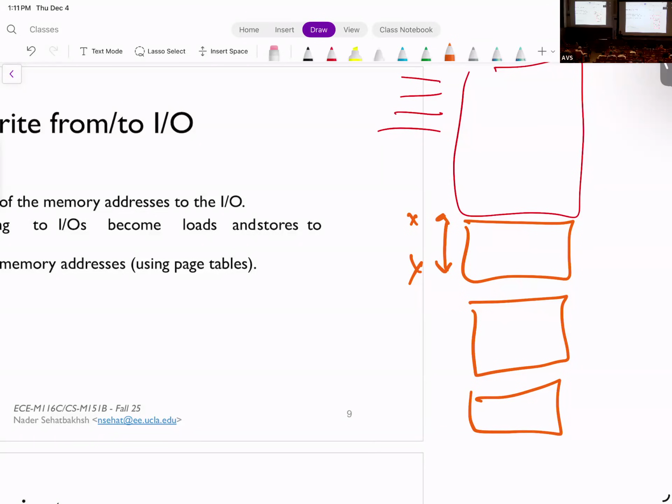You load and store, and only the address changes. Then all those tricks that we discussed in class about virtual addresses, physical addresses, address translation, and caching apply here as well. All you need to do is tell your system that you have this IO installed in this address range. So if you want to talk to your keyboard, here is the code for how to address it.